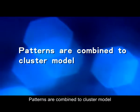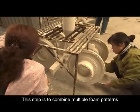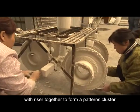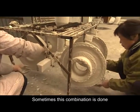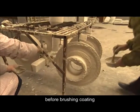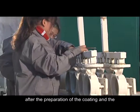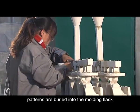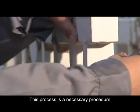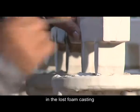Patterns are combined into a cluster model. This step is to combine multiple foam patterns with a riser together to form a pattern cluster. Sometimes this combination is done before brushing the coating. Sometimes this combination is done after the preparation of the coating, when the patterns are buried into the molding flask. This process is a necessary procedure in lost foam casting.